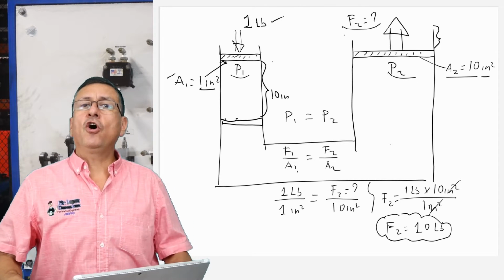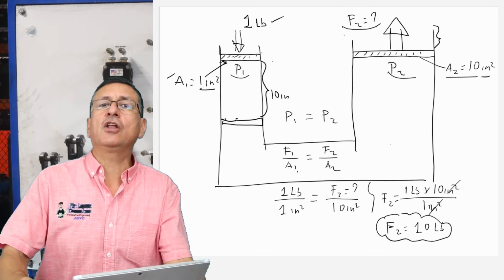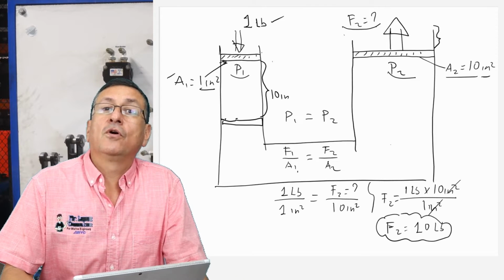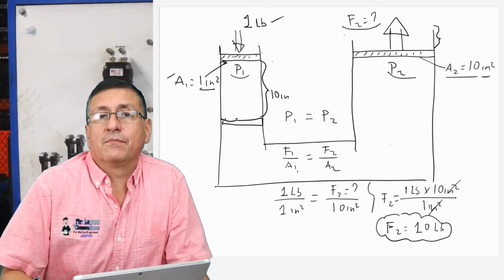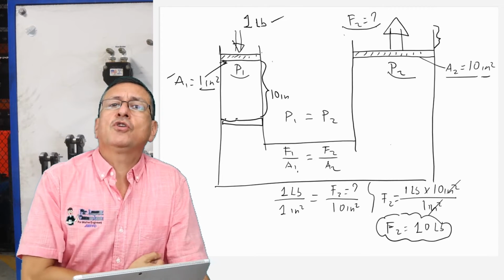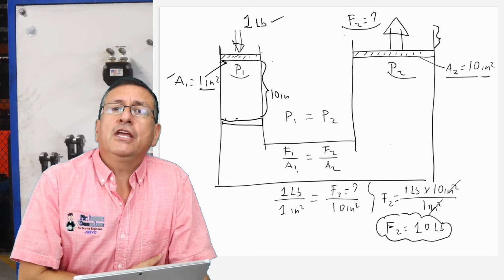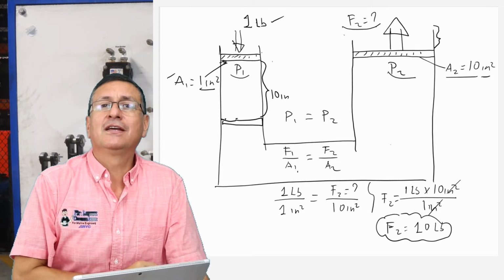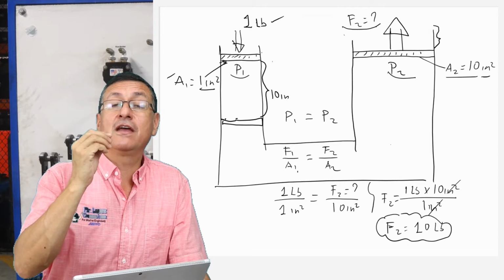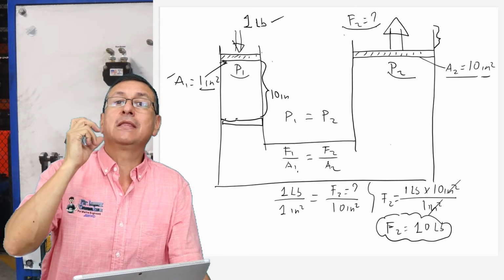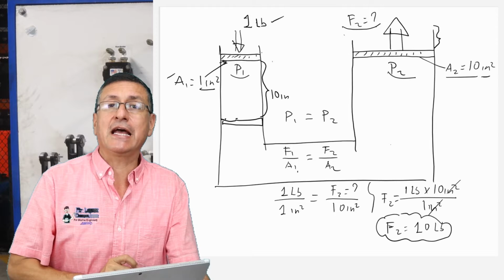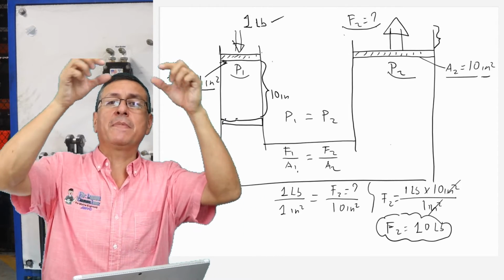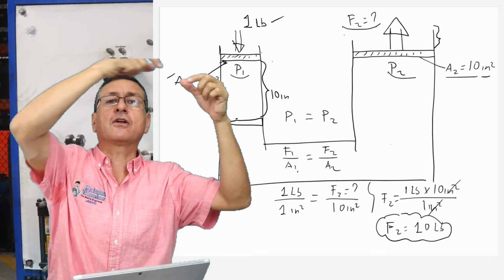Another system that is partially closed, not completely hermetic, is another hydraulic system: the motor oil, the oil in your engine. You remember the pressure on the oil pressure gauge? It depends on the film of oil in between the bearings and the crankshaft. But what happens when the oil reaches the top, on the rocker arms, to lubricate the rocker arms?